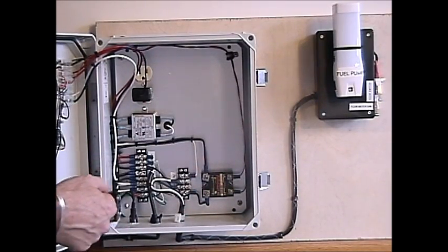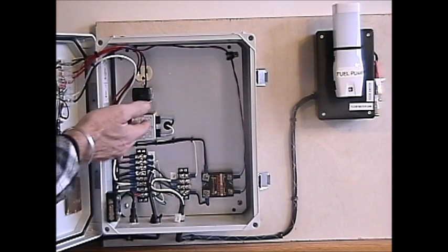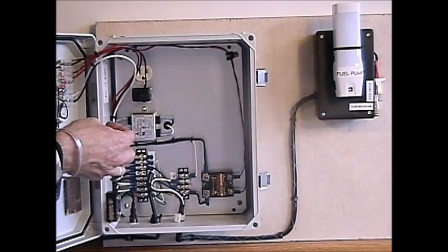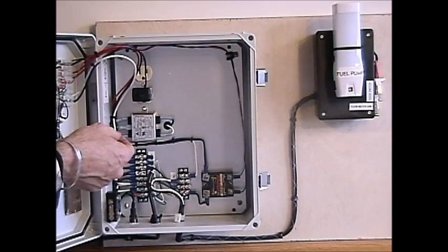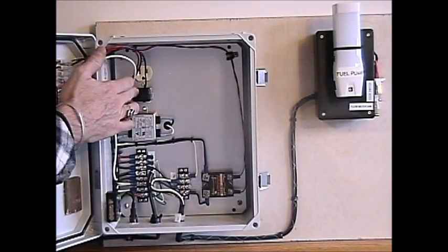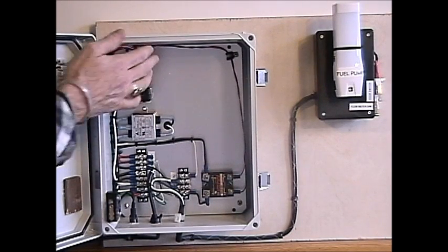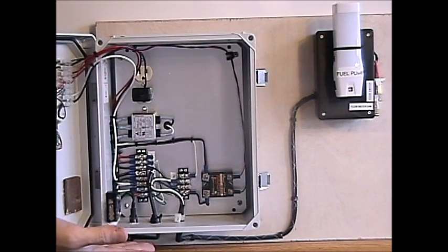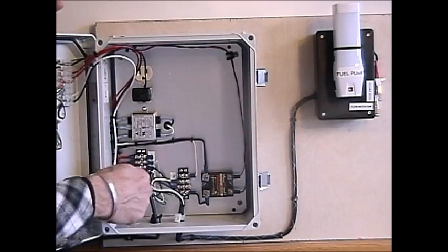Simply because that's just a high current, high energy circuit, and the conditioner for something with a 60 amp inrush would be the size of the box. So we don't need to worry about that, and that's fine. But we are conditioning power going to the logic section. That should be all that the electrician needs to worry about, is right in there.